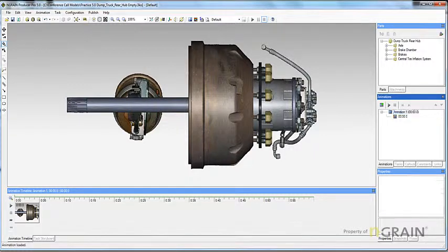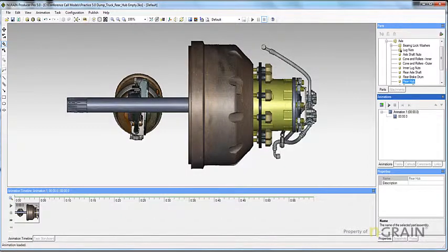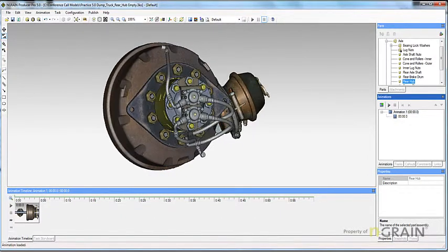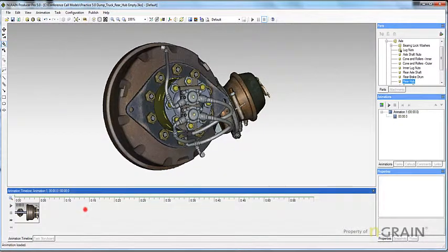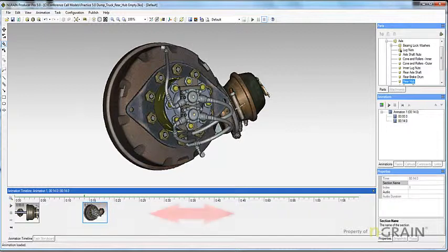For instance, if I rotate this object, come down in the timeline and double click, it will now take this model animation from the 0-second mark to the 14-second mark. If that's unsatisfactory, simply hold down your left mouse button and slide the second keyframe to the desired timing.